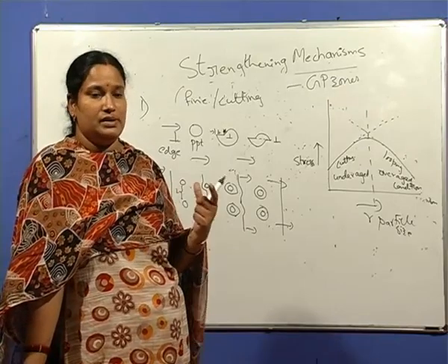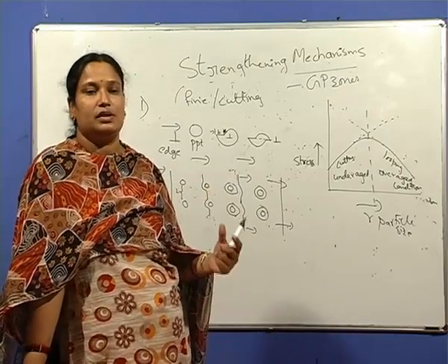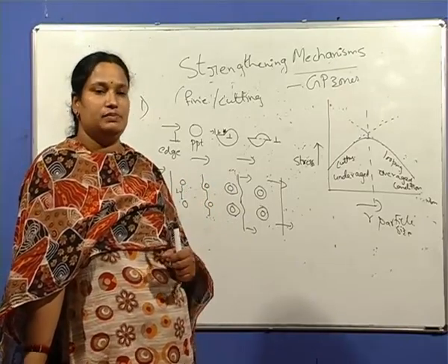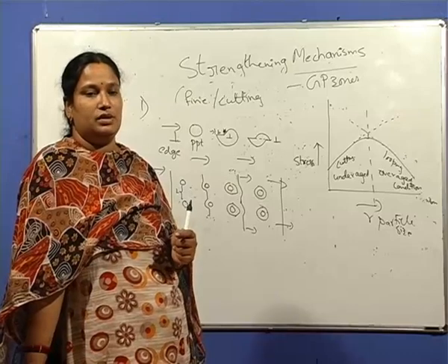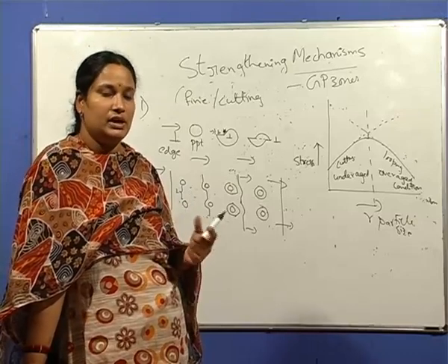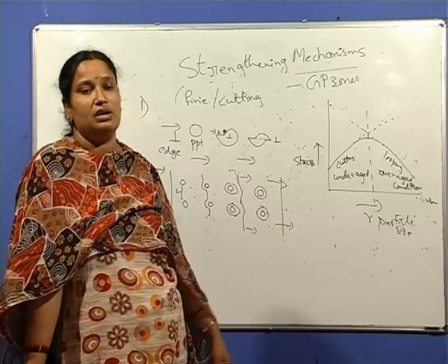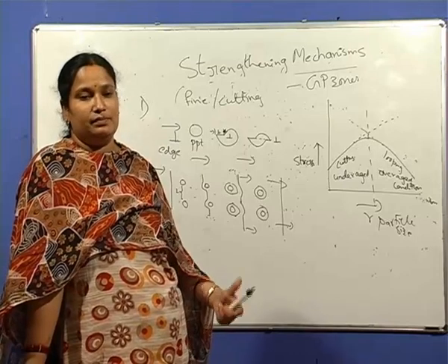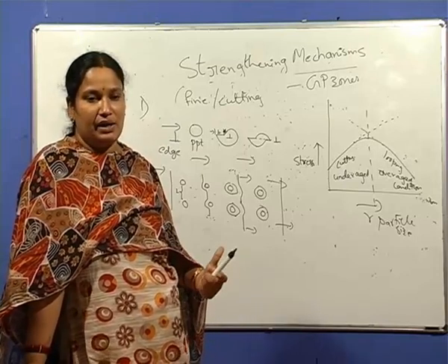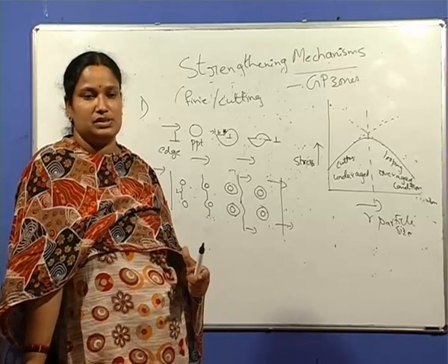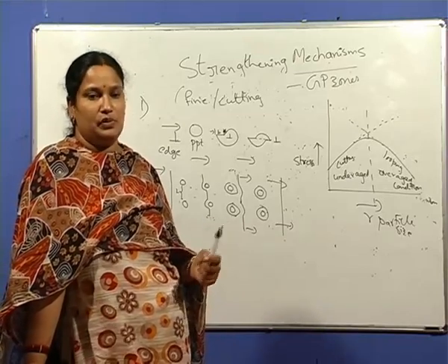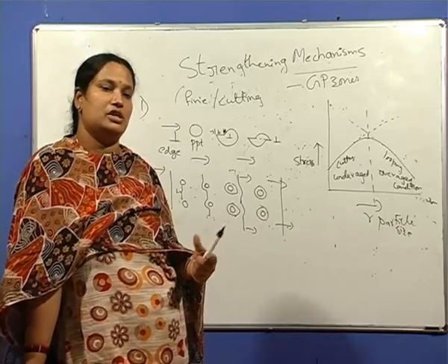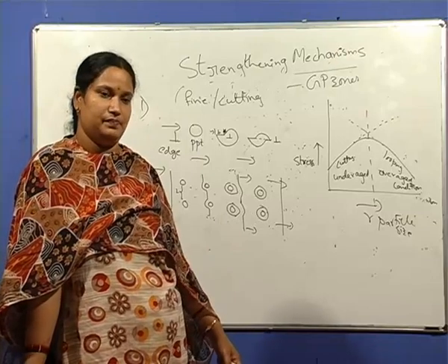Why are all alloys not precipitation hardenable? Because it requires some criteria for an alloy to be precipitation hardenable, that is the sloping solvus. Moreover, for dispersion strengthening, theoretically an infinite number of dispersion strengthened alloys can be fabricated, because it is simply mechanical alloying, mixing of metal matrix powders and inert oxide powders in a high energy ball mill, and then consolidation by compaction and powder metallurgy techniques.